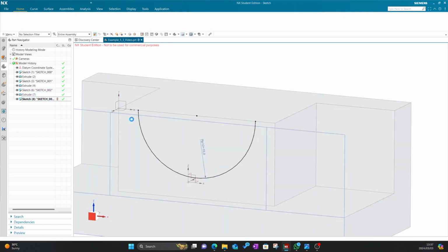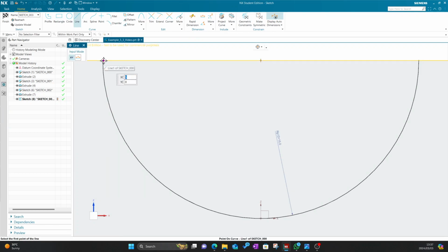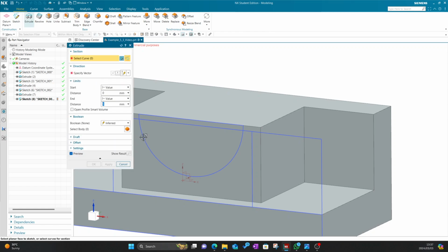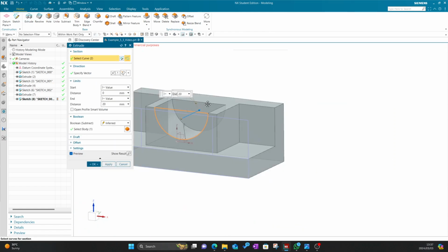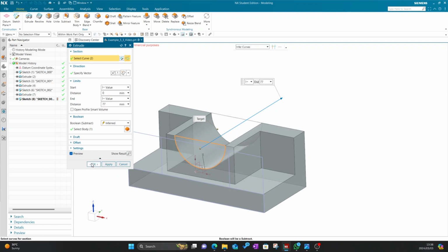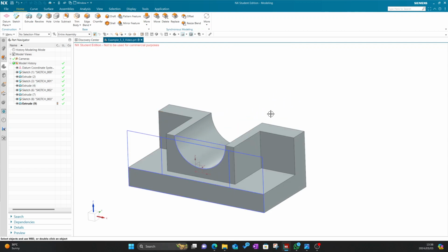So you need to make sure that you close the loop. So to close this loop, we need to add a line from there to there. And now we can finish. And now if we extrude this sketch, you'll see, okay, now it extrudes an entire three-dimensional model. And for cases where this thing goes right through, it doesn't matter how long you make it, as long as you make it long enough to create an extrude right through, because if you just take it to there, that's not correct. So for this model now, you can just swipe it through and click OK. So that part going over there doesn't matter.